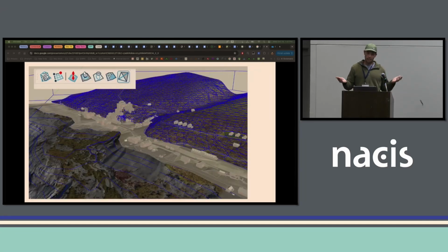And so once again, I like things that are flat. I like things that are easy to work with. I don't know if it's obvious from here. SketchUp also has some great terrain modeling tools that are limited in the type of scale that you can use. But what I've done here is I've cut out the core corridor of where all these buildings exist and then created a series of flat planes at their accurate elevations rather than relying on topo that moves in different directions.